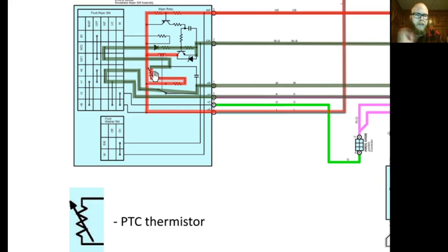It's like, I'm hot and it's too much work. I'm not going to do anything right now. No current gets to go by me really anymore. And the relay turns off. The park circuit runs and allows the full wipe to happen. By the time it's come back, this thing is starting to cool off. My voltage on the ground side of this is building. The current flowing through it begins to increase to the point at which I can actually flow enough from my base to my emitter to allow my higher current to flow from the collector to the emitter. And then my relay's coil turns on. It pulls this switch up and supplies power to it, and the wiper goes off again.